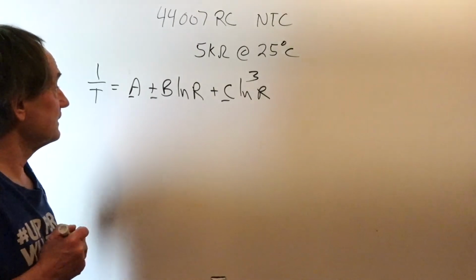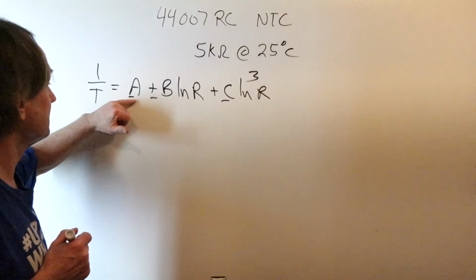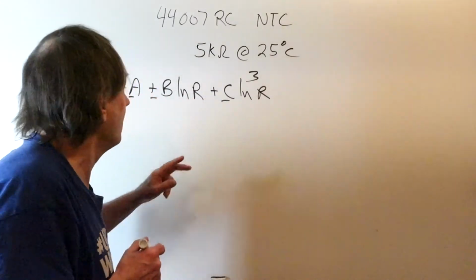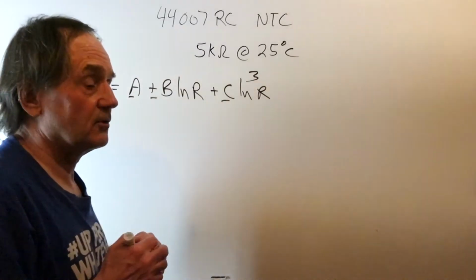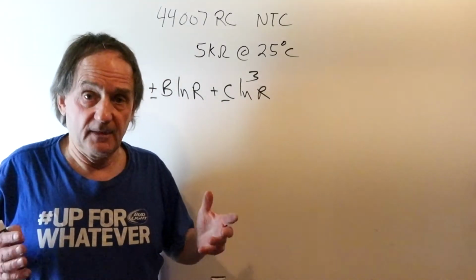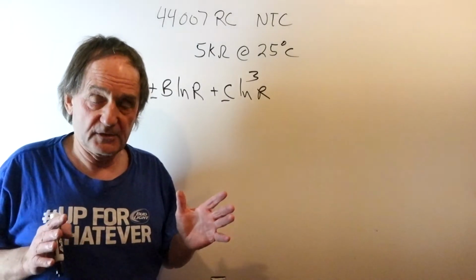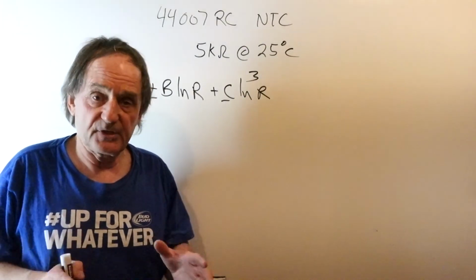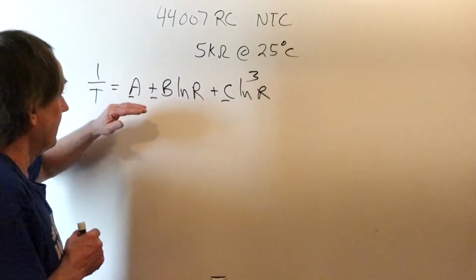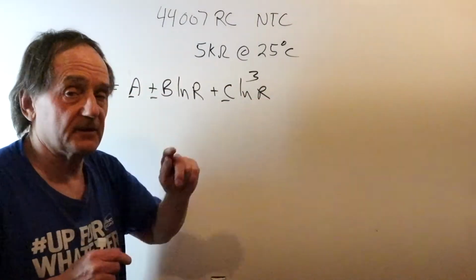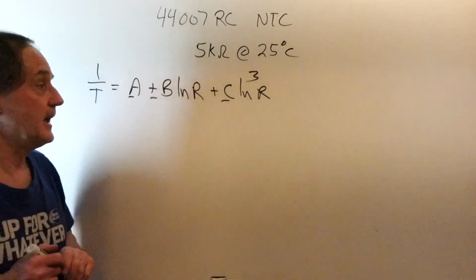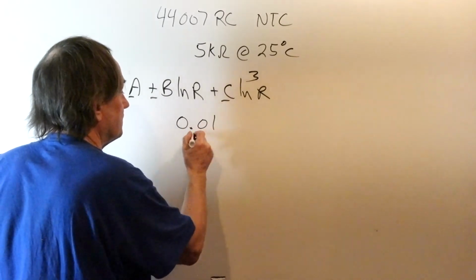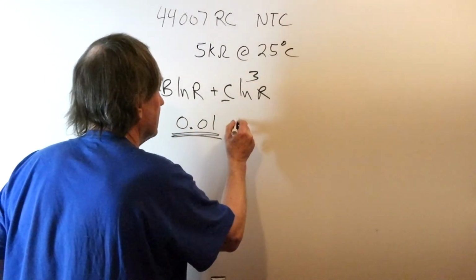However, I've taken it a step further than this. I've actually determined the A, B, and C constants for each one of the 5 thermistors on my pole by calibrating each thermistor in an ice water bath whose temperature was established using laboratory grade precision thermometers. So I have these thermistors on this array very well characterized, and I can determine the temperature to within 1/100th of a degree Celsius.